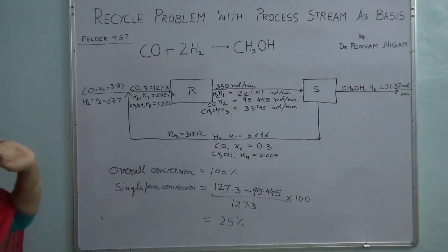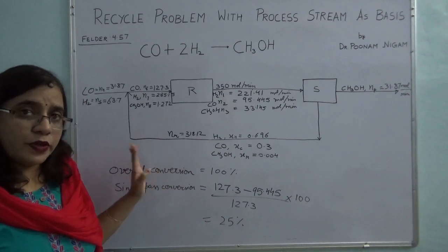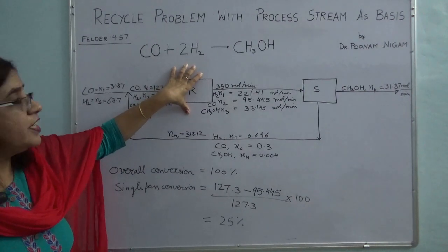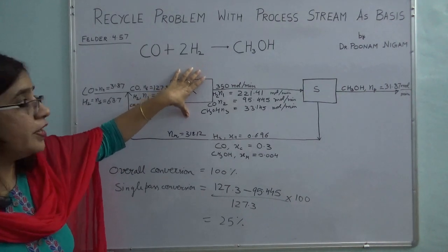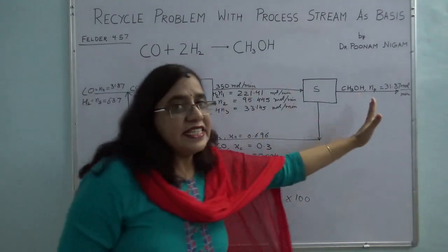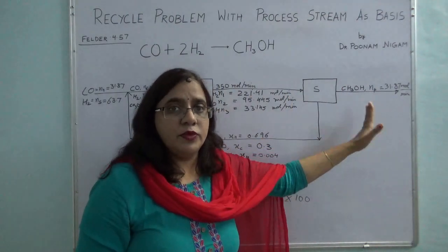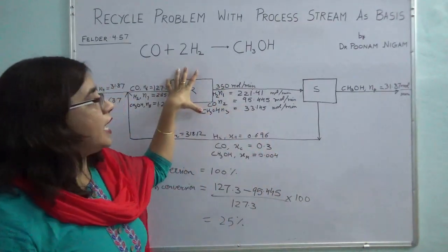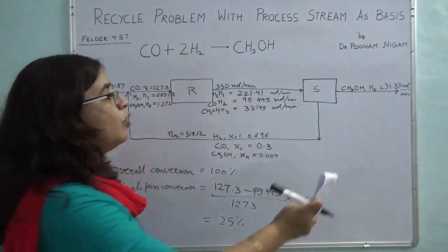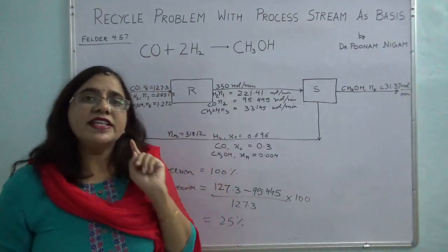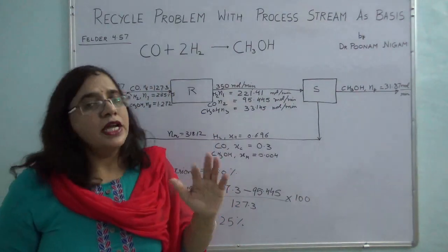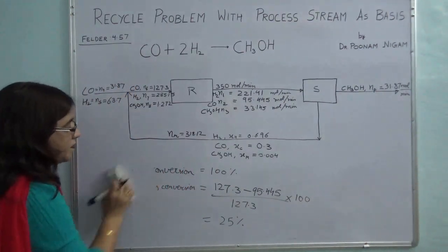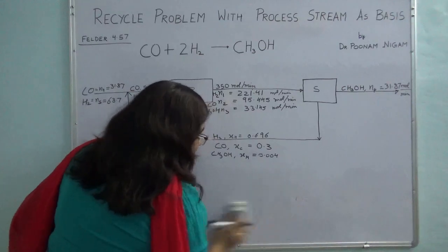Let's see, if I ask you what is the extent of reaction, then you may be confused whether you want to base your extent of reaction calculations over here or on the entire system. So I will tell you, it doesn't matter whether you base your calculations on the reactor or on the overall system. Whatever extent of reaction you are calculating, it remains the same. Let's first calculate, and then I will give you an explanation.